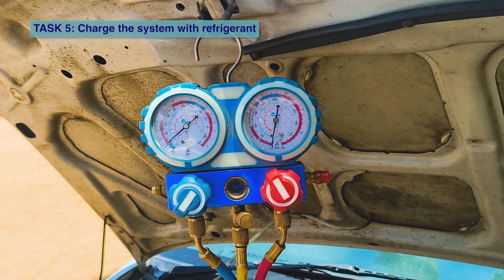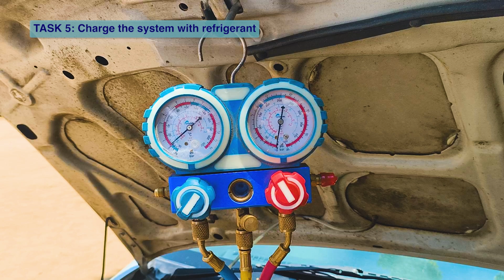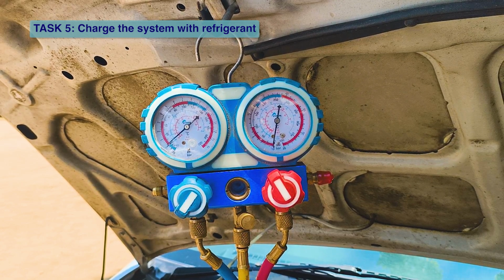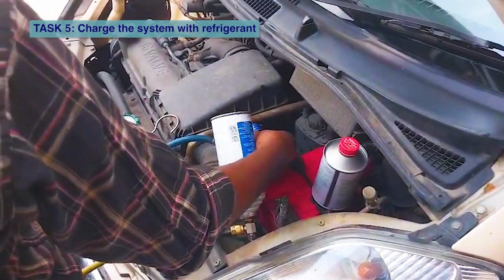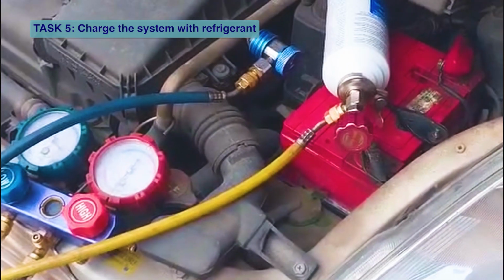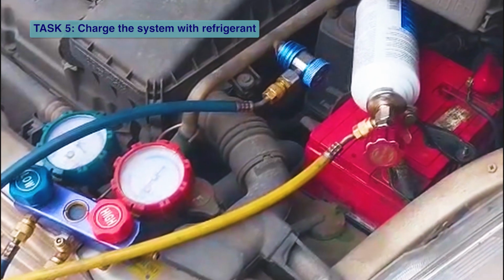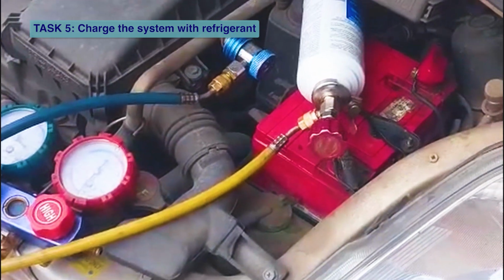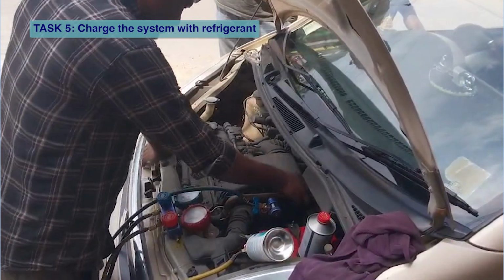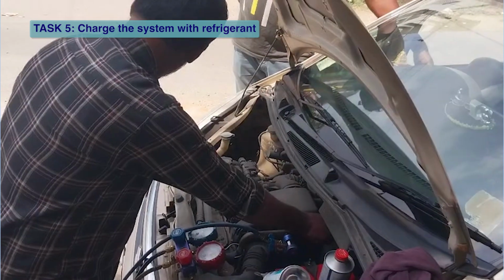Ensure that the system is fully evacuated before starting the charging process to avoid introducing moisture into the system. Ensure that all machine valves are securely closed. Place the refrigerant 134A can in a suitable position and open the can valve carefully. Monitor the refrigerant 134A can as it is being transferred to ensure the correct amount is charged.